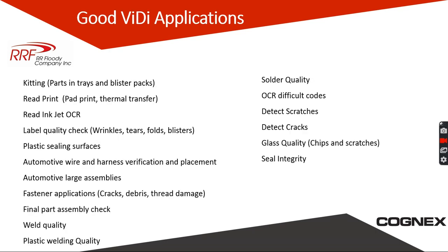Here's just a list of all the good applications. If you've been in vision long enough, you see some of the applications we used to not entertain very well. Look at it: detecting cracks and scratches, solder quality, weld quality, plastic weld cracks, difficult to read, glass, looking at quality within glass, and seal integrity, which has always been a tough one.